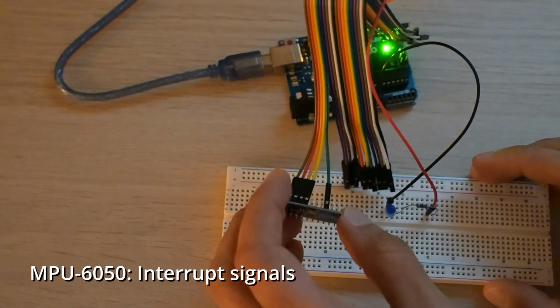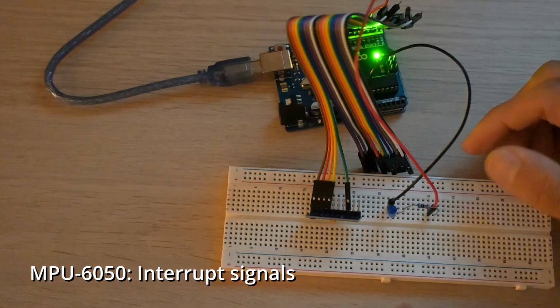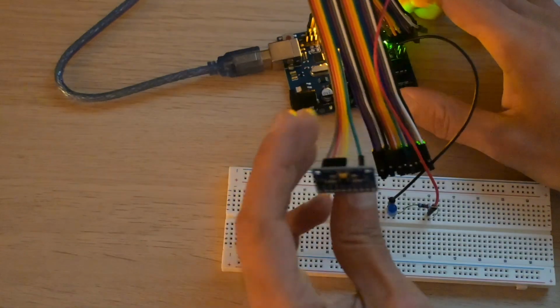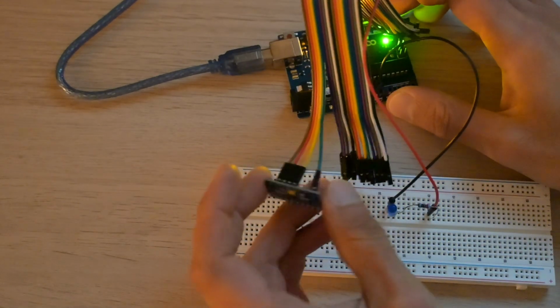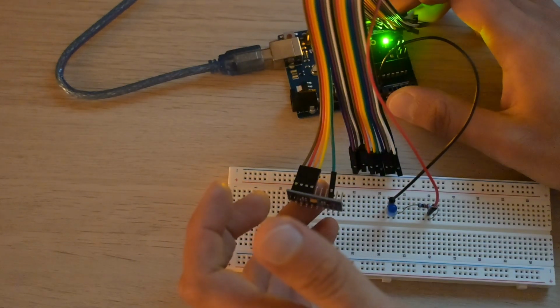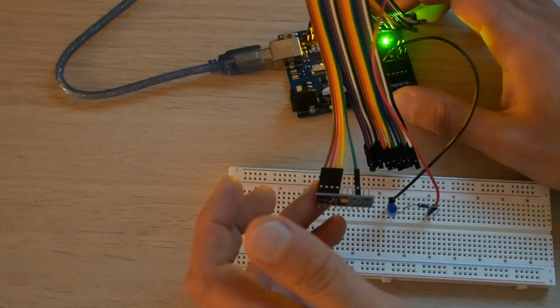While going through the datasheets of the module, I've noticed that it could be commanded to dispatch an interrupt signal whenever a certain threshold of movement was detected. This could be useful for low-power systems, for example, where the interrupt would flag that relevant movement data was starting and the main controller should transition from a standby state to a fully active and powered state.